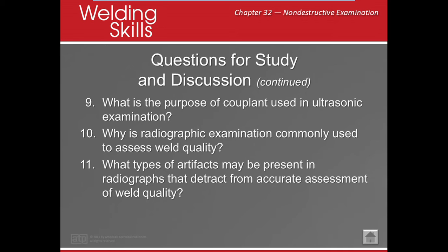Why is radiographic examination commonly used to assess weld quality? Well, RT is used because we can see gas pockets, slag inclusions, porosity, cracks, or lack of penetration. It outlines the defects and we can see where it is in the weld. That's why it's used more often.